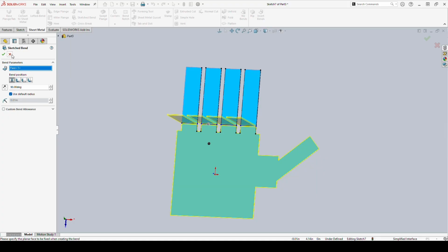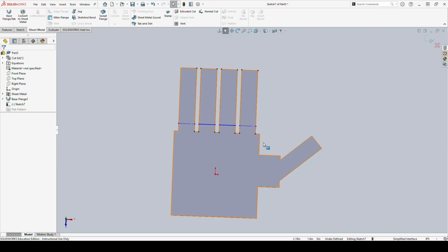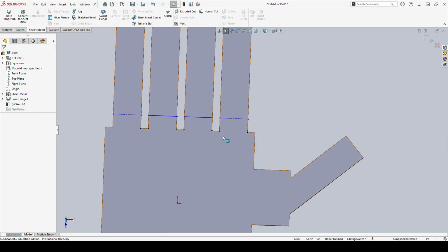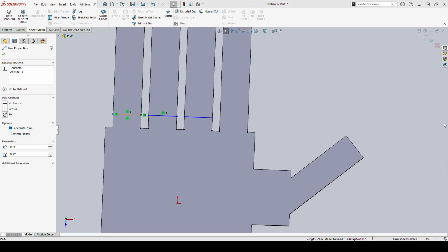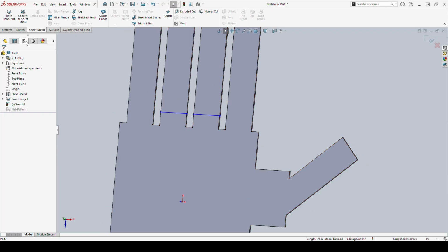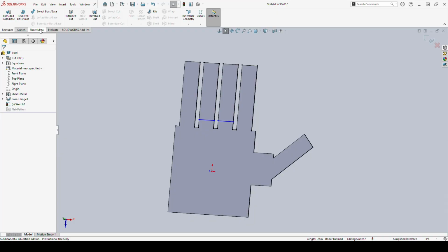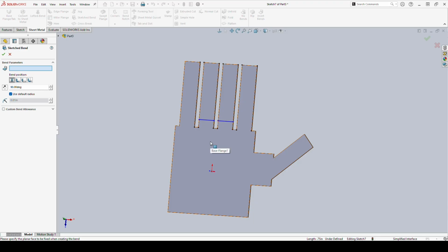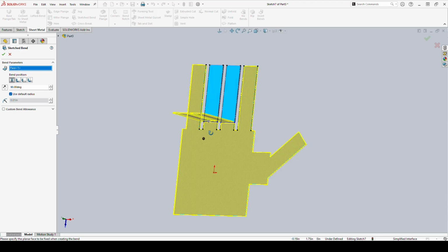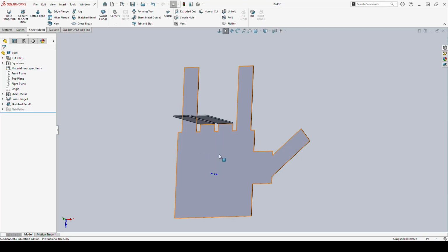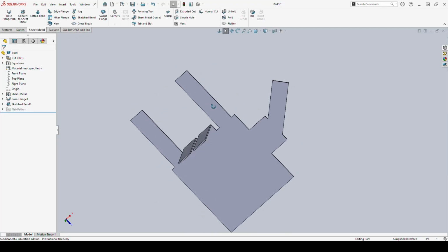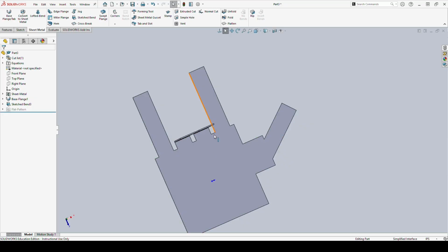If we went through and updated it, if we did this 10 times, 9 times out of 10, SolidWorks would probably catch it and would not rotate those. In this case, since we're in the middle of the video, I'm just going to go ahead and delete the pieces so that I know for sure I am only rotating the 2 fingers that I want. I go back and I do exactly the same thing. And in this case, I have only rotated the 2 pieces that I have lines between.